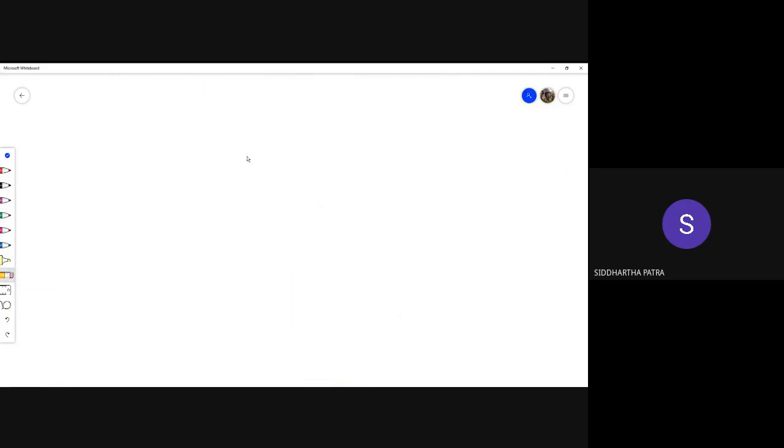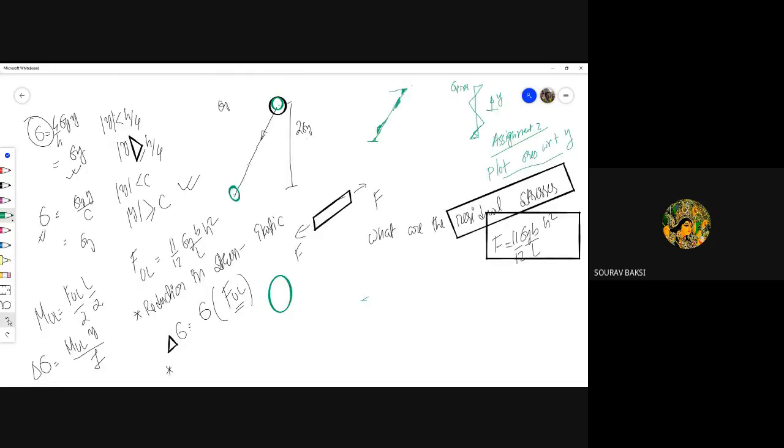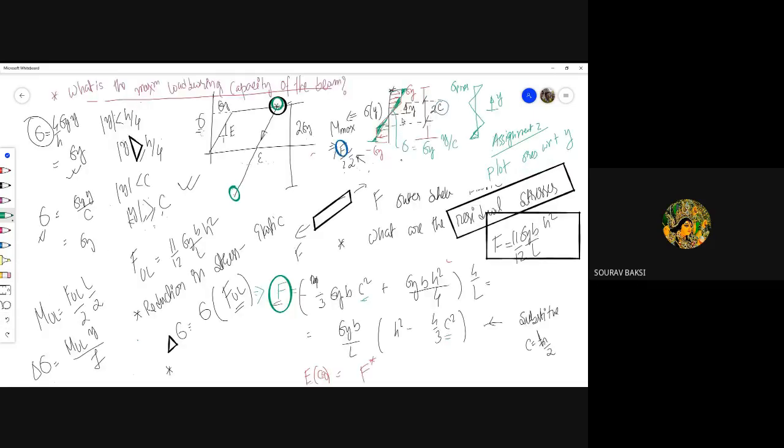So we talked about reaching certain residual stress, how the residual stress becomes greater than sigma max; I will say that again. The actual residual stress can be greater than sigma y, not sigma max, greater than sigma y. Okay, why can it happen? Because this is your elastic unloading window which has a size of twice sigma y. It can go from plus sigma y to minus sigma y.